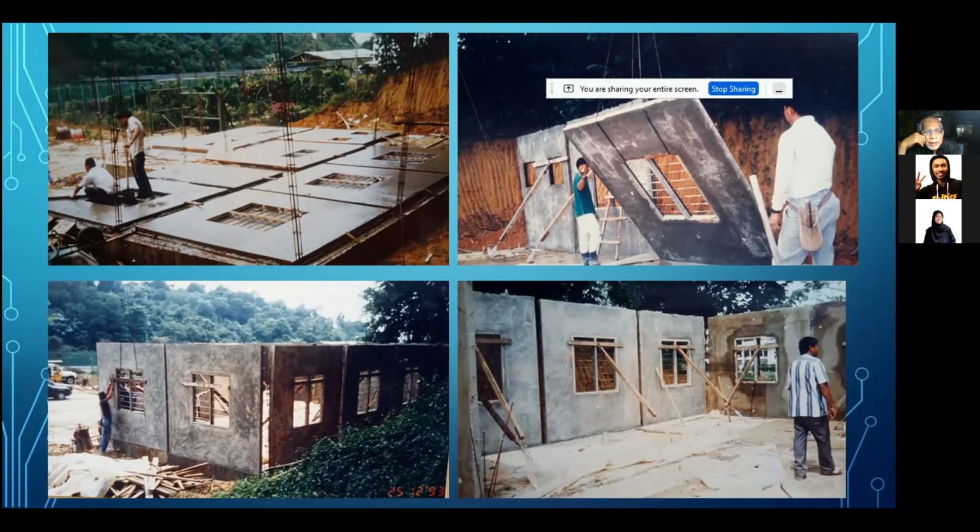I mean, sometimes you can control this because it can be wavy. In this case, with the small framework, the formwork is like 100 mm thick all around the wall slab there, so you can use that as a guide. You put a bit of cement and then it becomes very smooth and very flat. Even the door frame and the window frame are the same size as the perimeter formwork. And then once it is dry, we lift up.